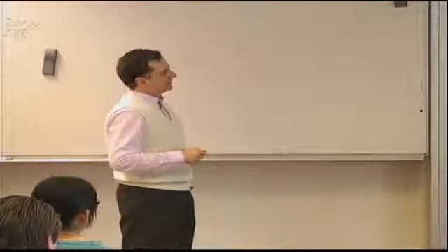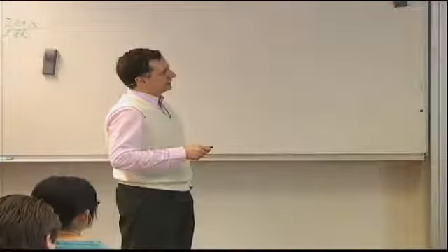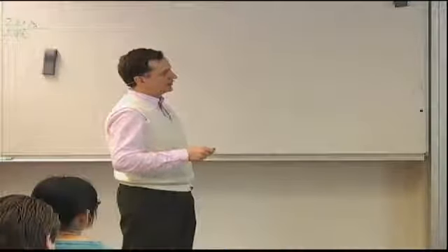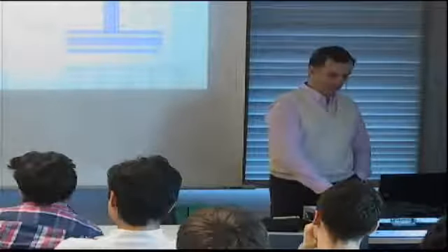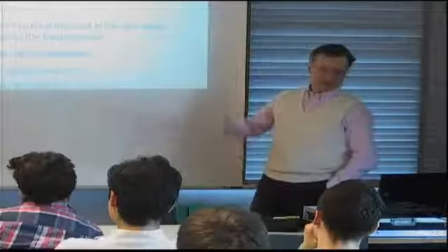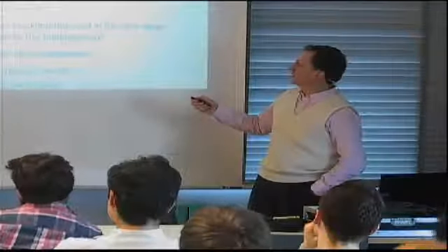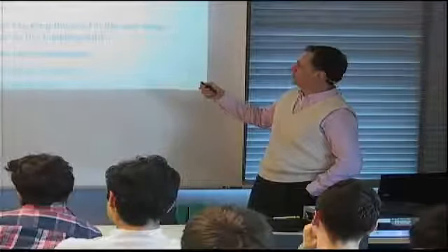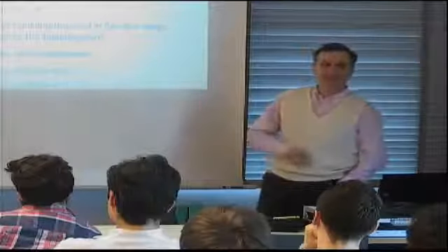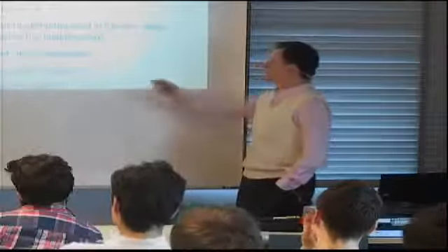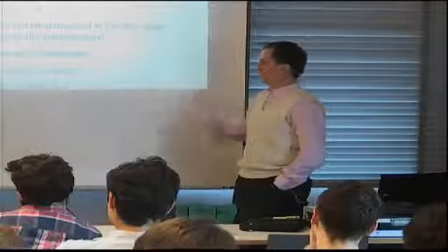And that means now that my post-buckling ratio, which is the ratio of the total applied load, divided by 457, which is the width. So this is 100 kilonewtons, divided by this makes the load force per unit width. And if I divide that by 182, which is this buckling load, I get 1.2. That means that the skin buckles, and in order to reach the full 100,000 newtons, I would need to keep increasing the loads by another 20%.